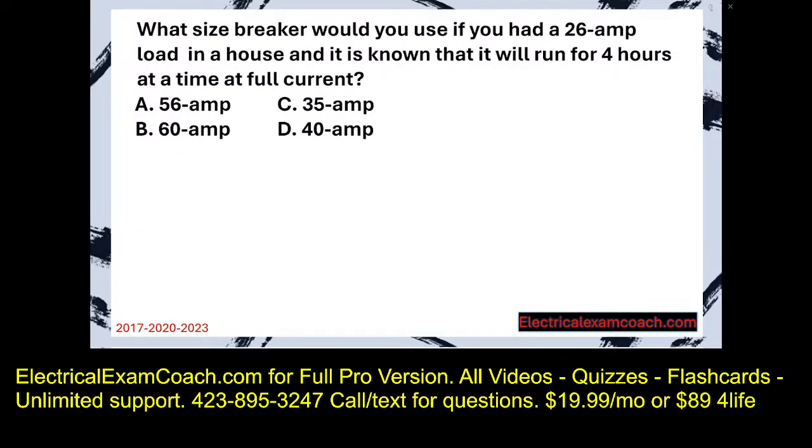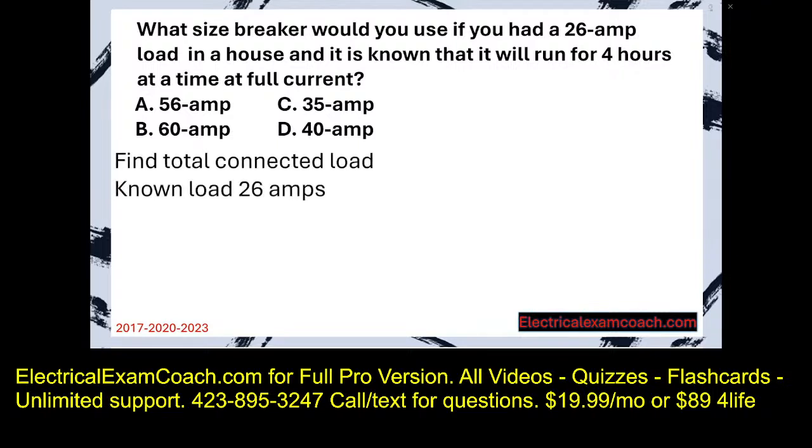What size breaker would you use if you had a 26 amp load in a house and it's known that it will run for 4 hours at a time at full current? Step 1, find the total connected load. Our known load as of right now is 26 amps. Now we've got to check for demand factors.